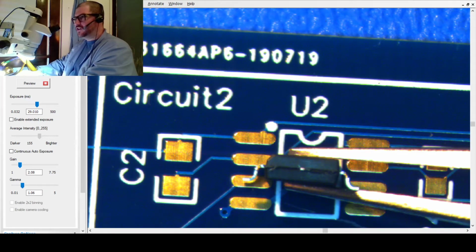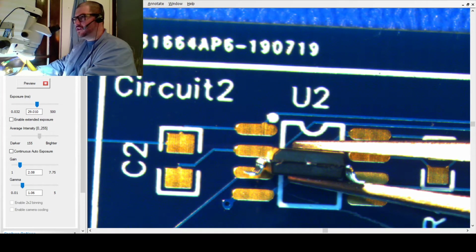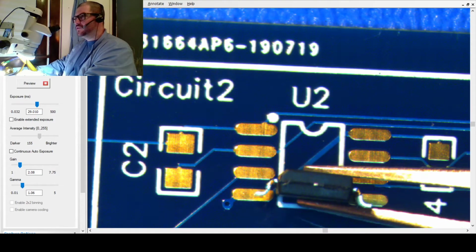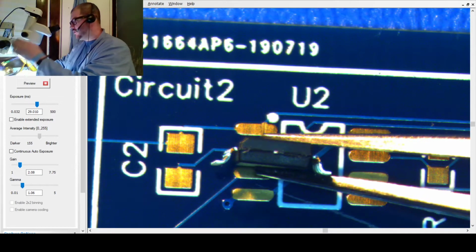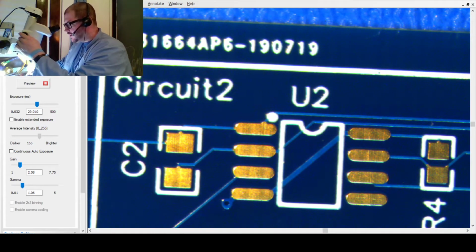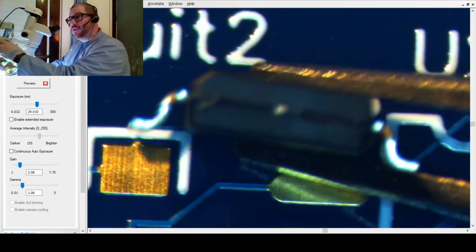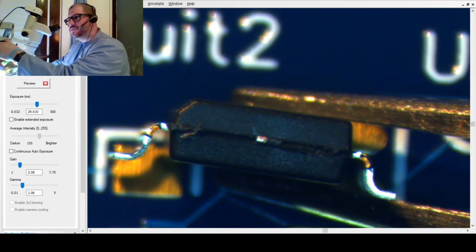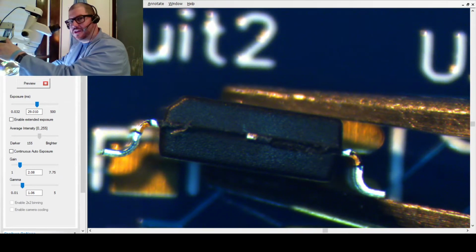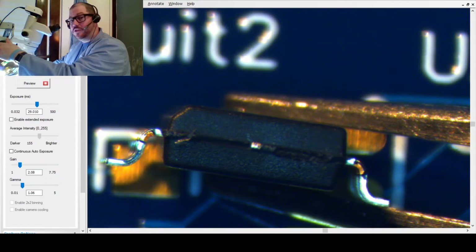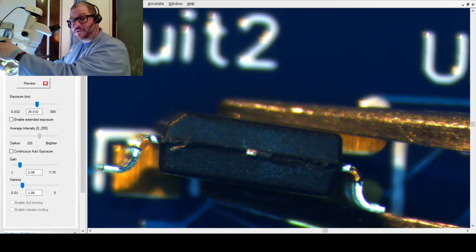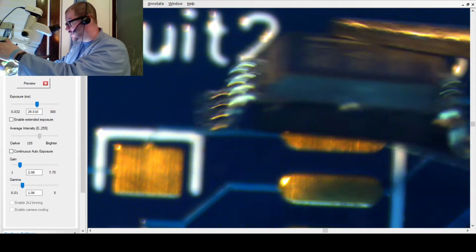But if one were to look at the chip, there is a little bit of angularity associated with the chip. If one were to look very carefully, one would also notice that there is a notch on the top left side of the chip. You can see that some chips have that notch, which can help to determine what the polarity is, depending on what the machine or the person is that's looking at the polarity.